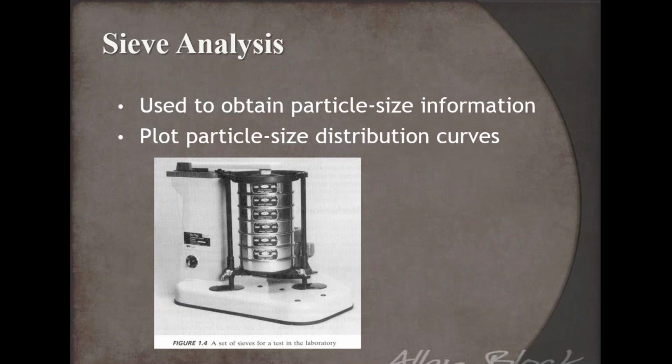So when you talk about particle size, this has been the time-tested and true method of determining how big the soil particles are. This is a sieve analysis, and as you work down that column of sieves, the openings of the screens slowly get smaller. The top sieve will have larger openings, and it'll go all the way down until we collect it on what we call the pan down below. And you just shake the soil on there and let it work its way through.